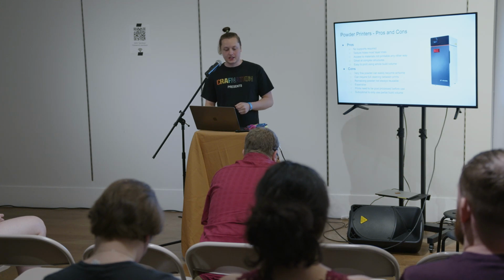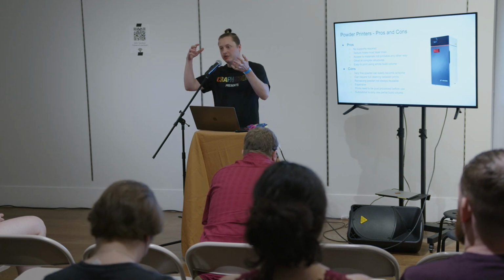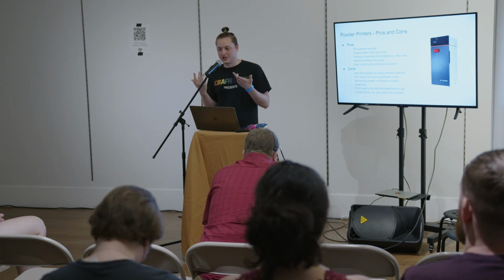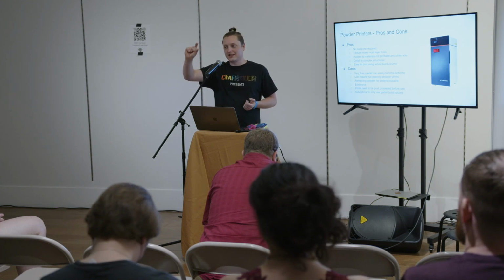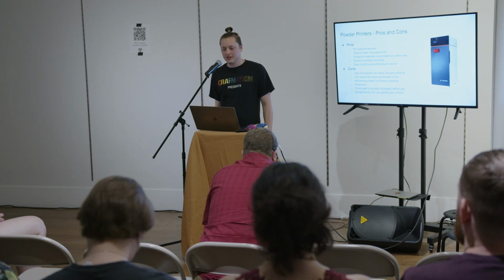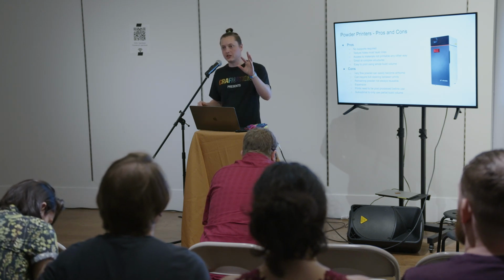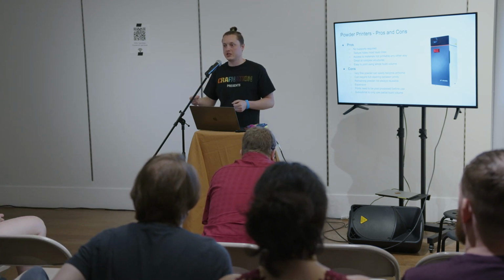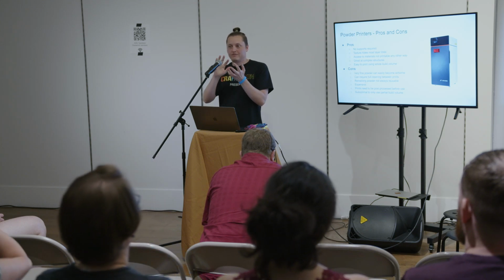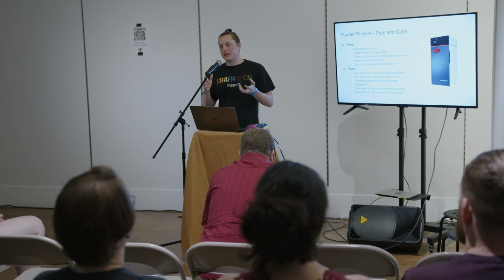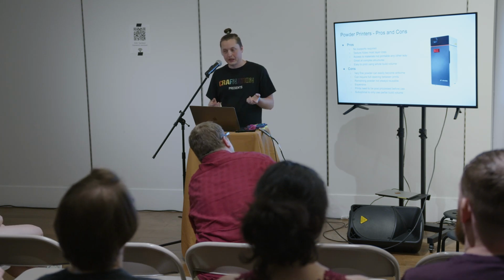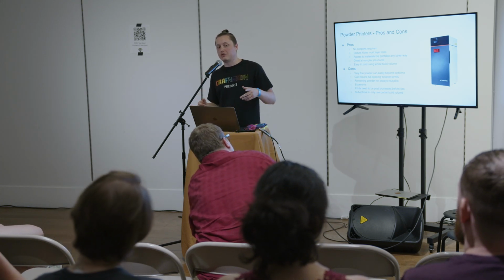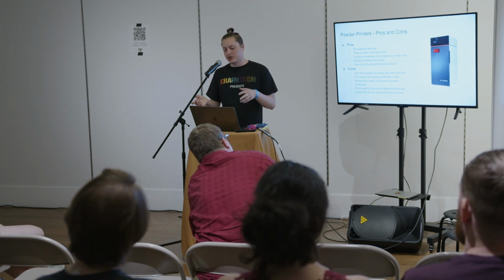Yeah, pros and cons. Pros: no supports are required, basically because the part is suspended in that powder. It's all the same weight. It doesn't sink into the powder and just stays. So you can get the little thing where you have a little ball inside of a cage, and that's all just printed together. The texture is essentially defined by the size of your powder, which is your detail definition. A lot of that hides the layer lines, so it's a much more uniform texture. You can have access to things that are not printable any other way, like metal, and it's great at complex structures.